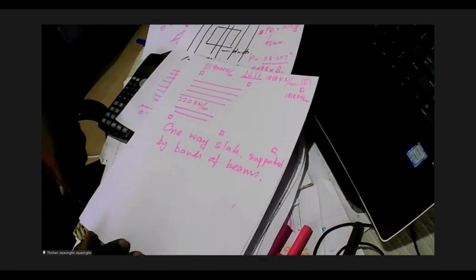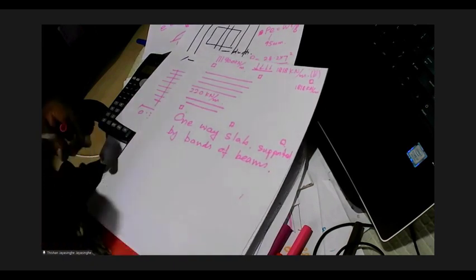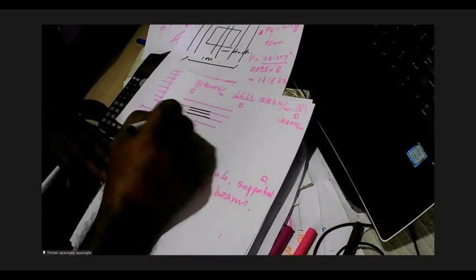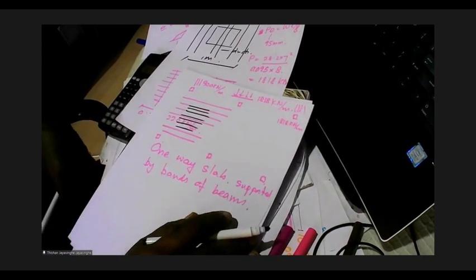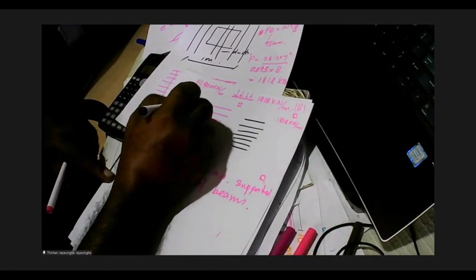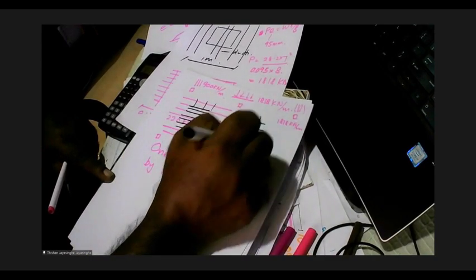Can you understand this, Bashika? So once you decide on the pre-stressing force like this, you might need some extra reinforcement in these regions, in that direction, and here also in that direction. And you might provide some distribution reinforcement in the other direction. So that will all depend on the stress diagram like this.